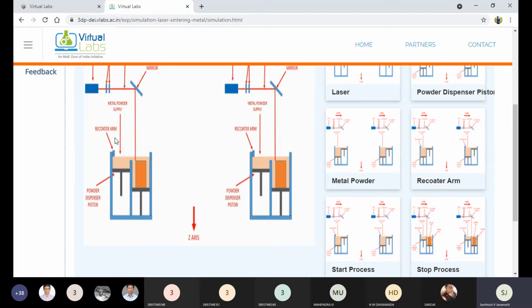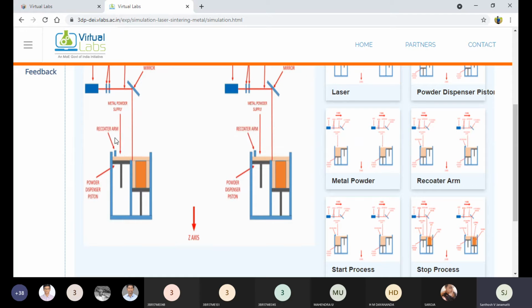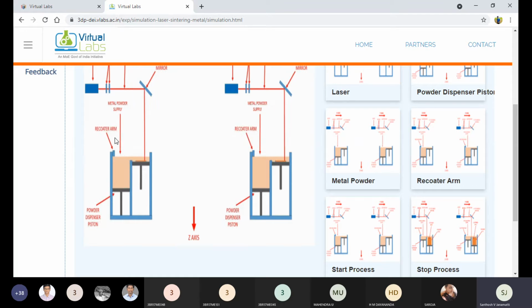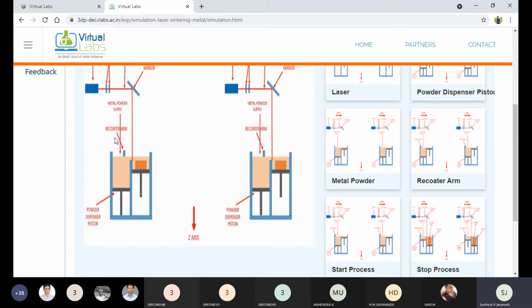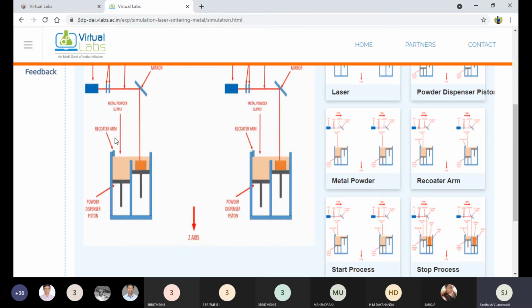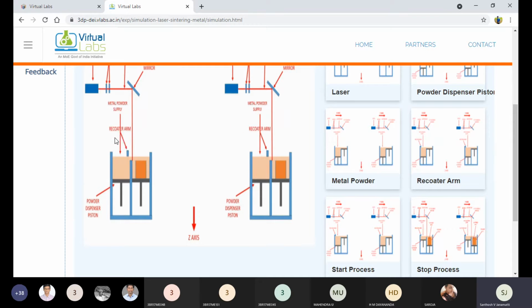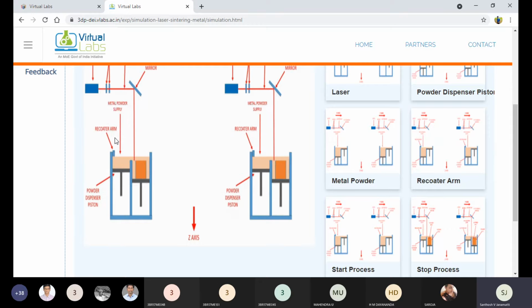So we need to ensure that the particles are dense. That is the reason we take roller mechanisms. But in metallic cases, the materials are already high density powders, so there is no need for rolling mechanisms. A simple arm, plate or doctor blade-like blade is enough to carry the raw materials, which are later fed over the platform.